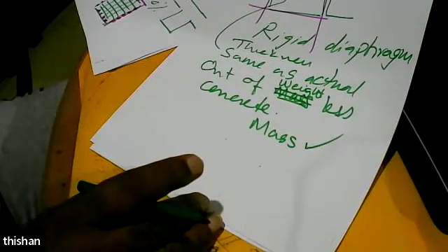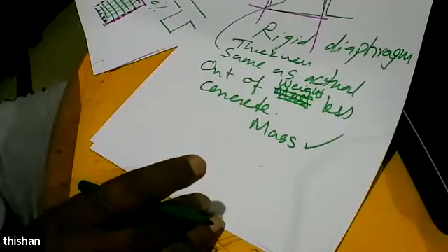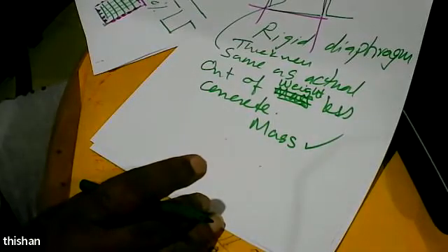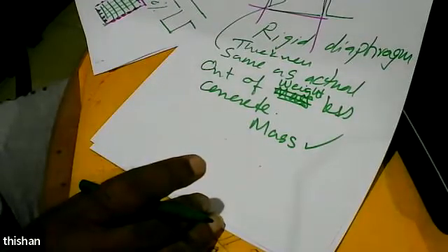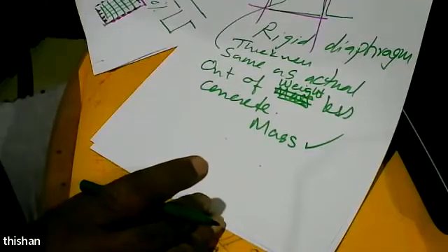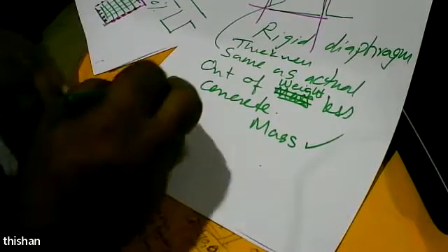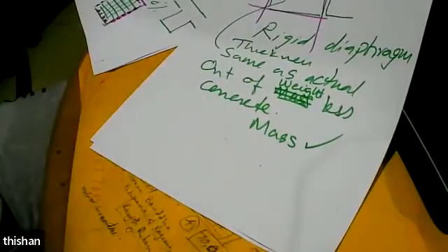how about the beams? And Eurocode gives some guidelines, but generally we can simply say beams are there. And beams are supporting the slab, and slab is actually doing a good service by assuring that people can use it, and also there's a rigid diaphragm. So it's a rigid diaphragm because we have it, and we have it everywhere. That means mass is distributed. And then mass is at the correct location.